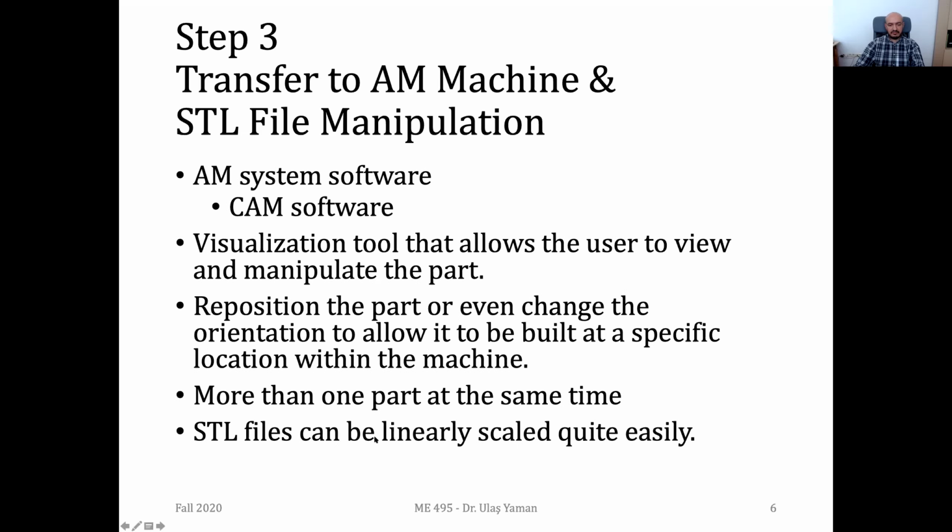And this is actually a nice property of STL files. You can easily scale them. Since we have a unitless file, you can easily add units to it and simply multiply the values of the coordinates, and you can have the scaled versions of your design easily.